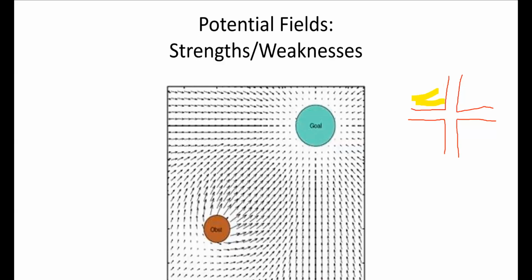So I have occupied space over here, and then my only free space is in that four-way. If I treat those flat spots as obstacles, then that might compete with my navigation function, right? The surface that's trending downwards. And so I have these traps essentially for my robot to fall into. But I can also navigate through this, right? I just have to know that it's okay to keep going.